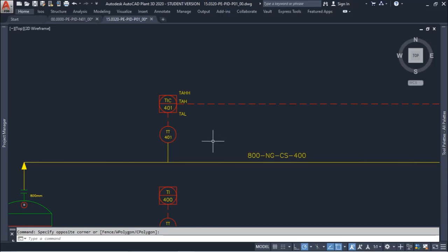For instance, if we are in normal operation, we have 40 degrees Celsius for the temperature of this natural gas stream. If we reach 30 Celsius, the operator will receive an alarm in the control room, telling him that something is wrong, but the system will keep running.